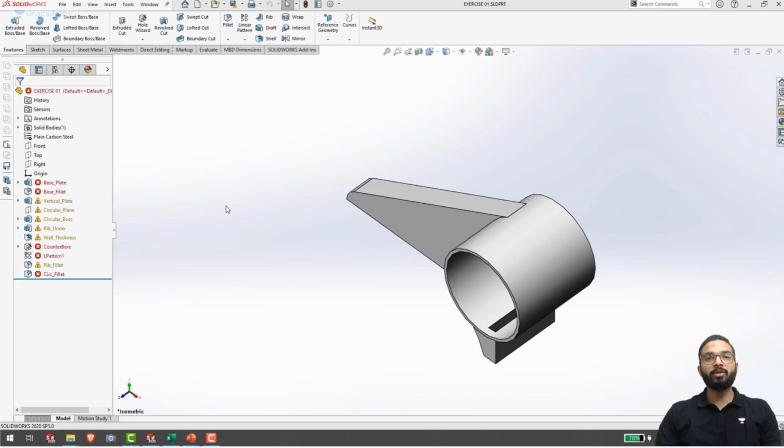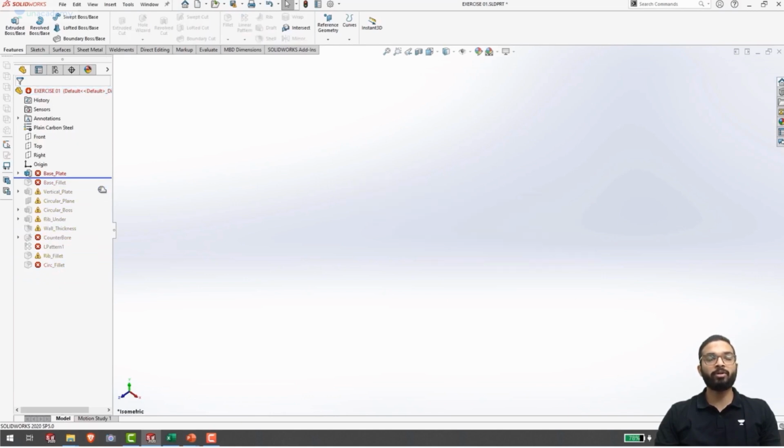In order to create any changes in your geometry or rather to rectify any problem in your geometry, it is always a good practice to first roll back this rollback bar up to the feature that you want to rectify. In this case, we would be rectifying the first feature as it is having problems in the first one itself. If I click on this over here, you can see that this warning or rather this error tells me that the sketch cannot be used for a feature because an endpoint is wrongly shared by multiple entities.